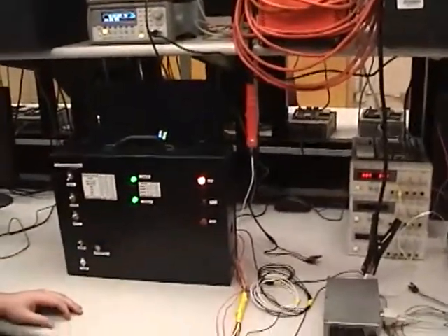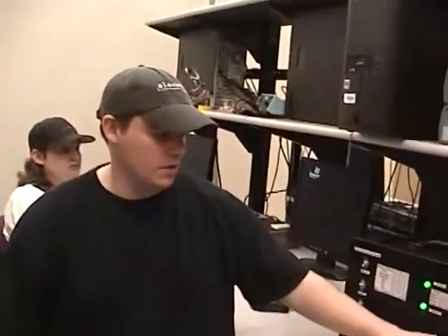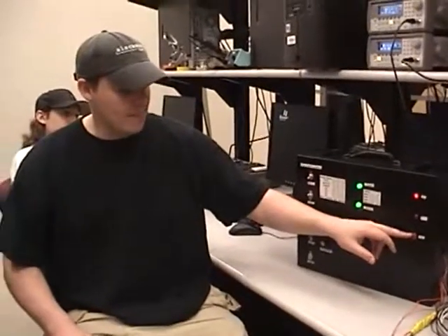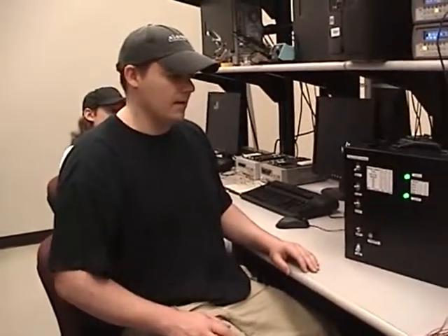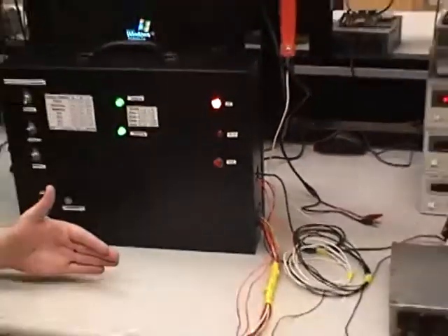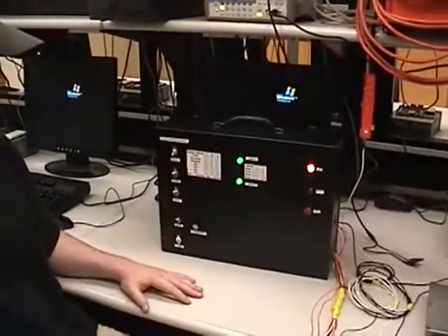This is the TCC solenoid, which is located in the front right here, and what that does is it locks the transmission to the engine mechanically so that there's no slippage occurring through the torque converter. Whenever the light comes on, the transmission is locked up. You only expect that in fourth gear when there's not a large change in speed, and the only other time is if the engine has indicated that it's overheating, and it's going to force it down to third, and either pulse the TCC or keep the TCC on to help cool the engine down as quick as possible.